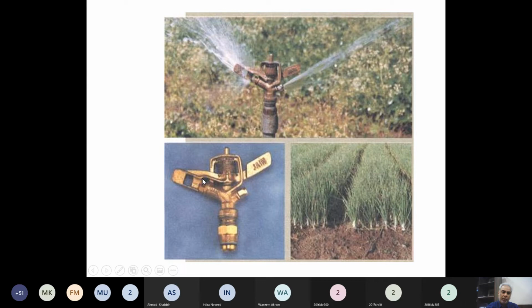When it comes back and hits the nozzle, it puts a force on this nozzle. It hits the nozzle, so this nozzle then rotates in the opposite direction. So over here it is rotatable. So after one impact, the vane goes in one direction and comes back because of the spring, and it rotates the jet to another place. So continuous application of this jet on the vane, and then the force of the vane on the nozzle, keeps it rotating in the horizontal plane.